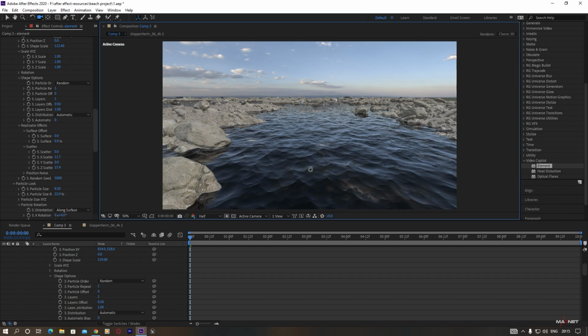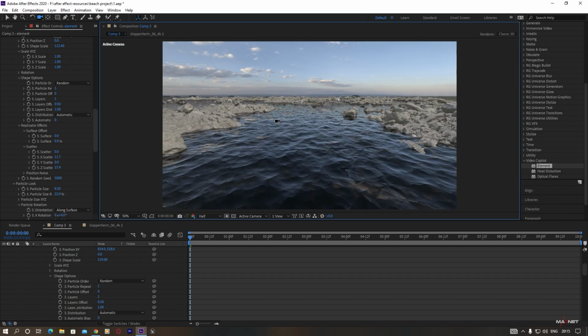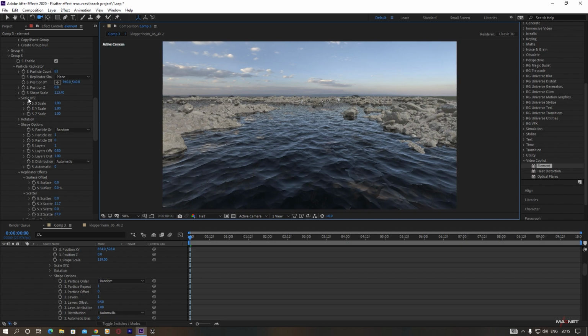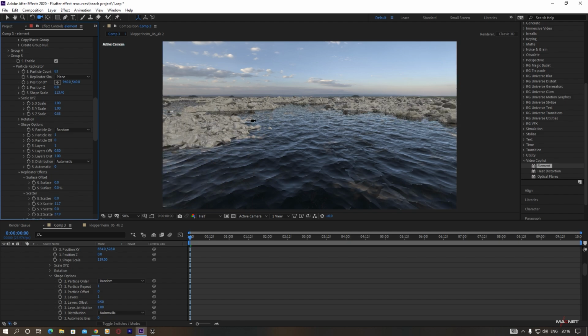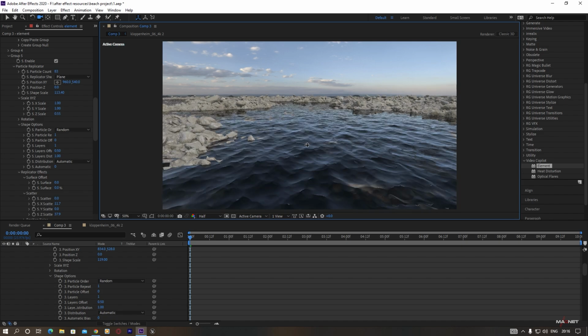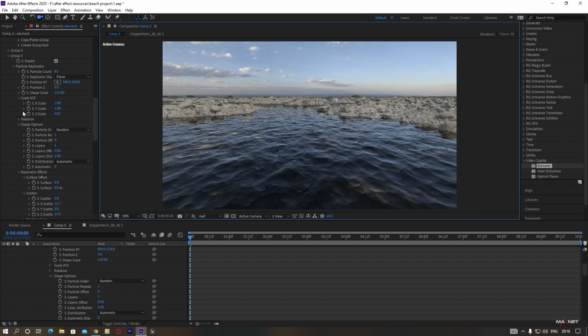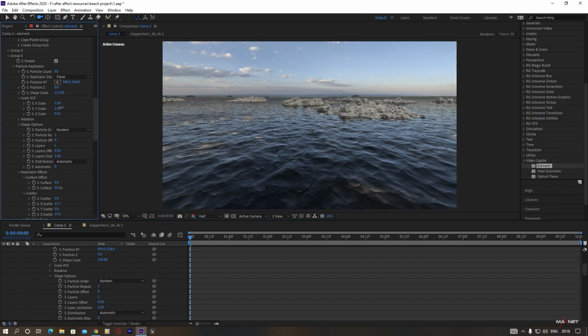So this creates a nice surface here, but maybe we want some of the rocky bed here, because we put the pillars here. So one thing we can do is go to the scale XYZ size here, and we can decrease the Z scale like this. Okay, and also we change the X scale shape as well. Just like this.